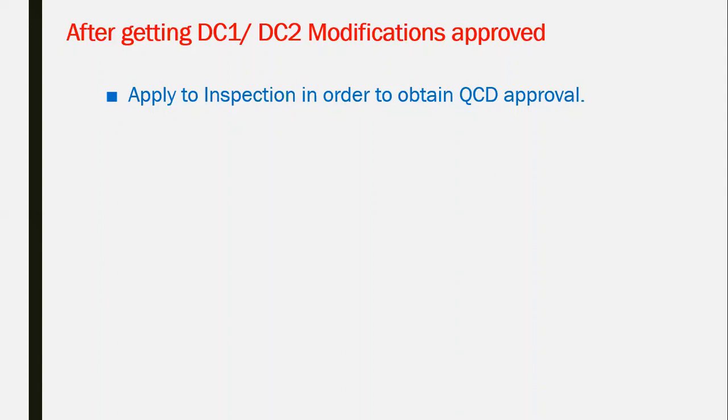In addition, you have to put a title and room number for each room, and it should match the mimic panel, which will be provided in the fire command center. They are going to check all of this.